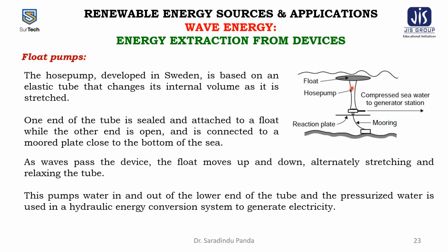This is the hose pump. This is the floating surface. Compressed seawater to generator station. This is the mooring. Reaction plate is here. The water is in and out from this narrow space.